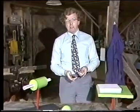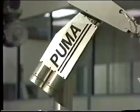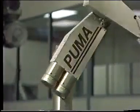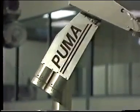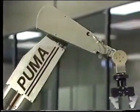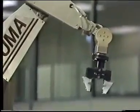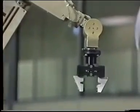Well, that's all 6 of Reuleaux's pairs, but what's all this got to do with the analysis of kinematic structures? What, for instance, has it got to do with Puma? The Puma is designed completely around revolute pairs. There are 6 of them arranged in series. So we have the first, second, third, fourth, fifth, and sixth.